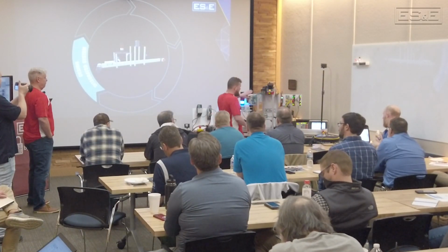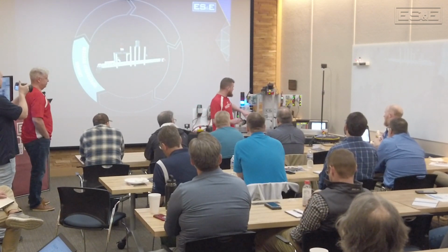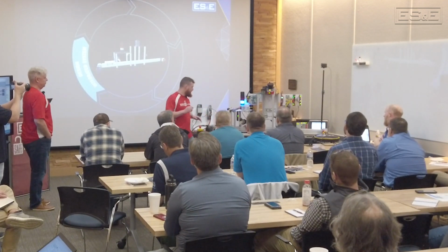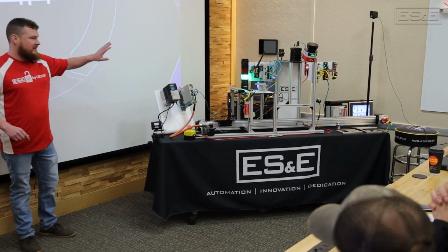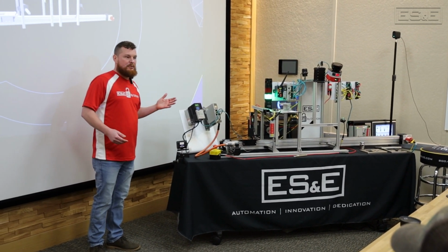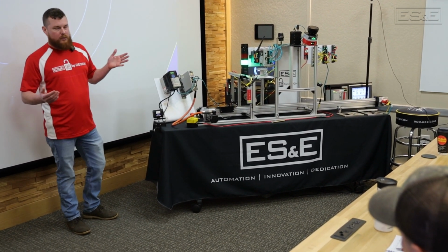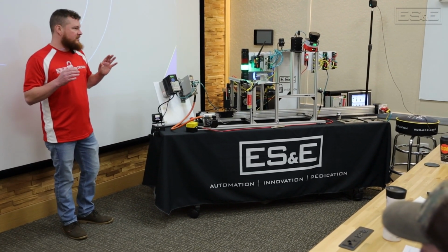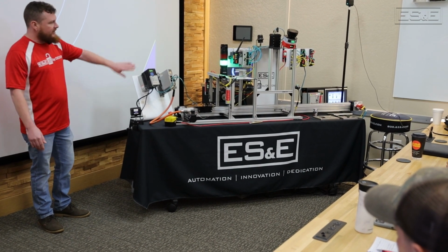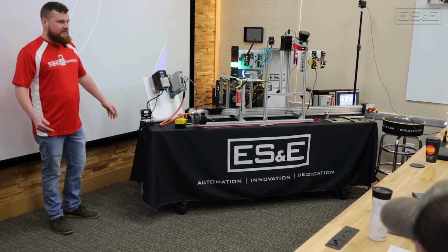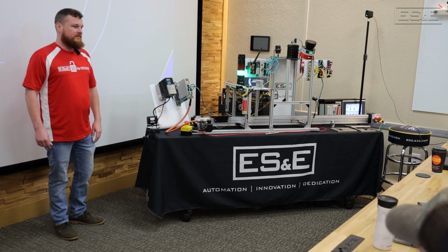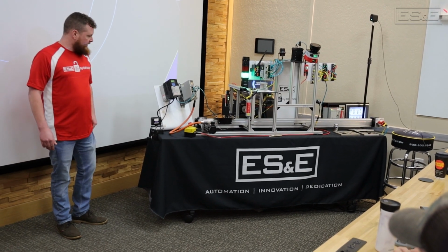Just to give you an example, you can see here I was in the orange zone. With these different zones, we've actually got different programmable settings. As it got out of the orange zone, it moved to green and moved at our fully operational speed. When it's in our yellow or warning zone, we've programmed it to operate at a safe, predetermined speed set in our program. When it's red, we prohibit this machine from operating to prevent any malfunctions or operator harm.